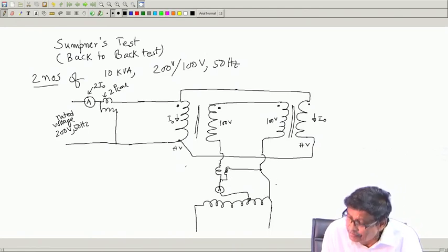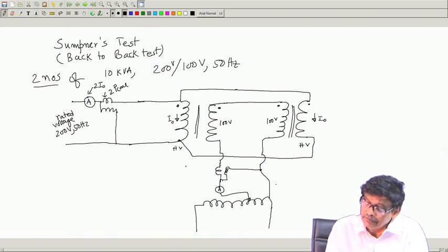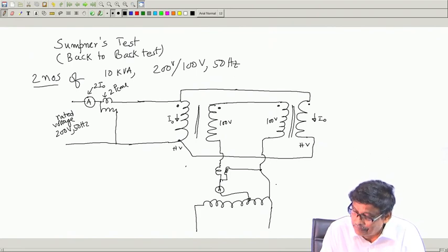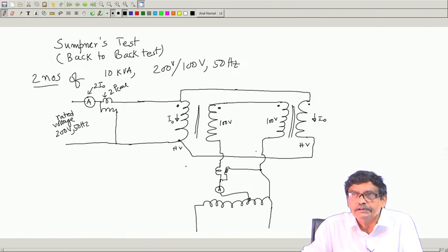Now, what you do with the primary energized, mind you, you apply a little voltage, increase slowly. Then what will happen? What is the net EMF acting in the circuit now? This 100 volt will cancel out, they are as if not there. So, applied voltage divided by the impedance, so apply a little voltage, current will start flowing, is it not?